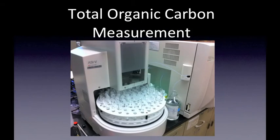Total organic carbon is usually used as the indicator of water quality. It is measured by the TOC analyzer. It measures the amount of inorganic carbon evolved from an acidified part of the sample and the amount of total carbon present. Total organic carbon is calculated by the subtraction of inorganic value from the total carbon. During my research, I was able to lower the detection limit of TOC analyzer from 10 mg per liter to 0.08 mg per liter by increasing the injection volume and number of injections.